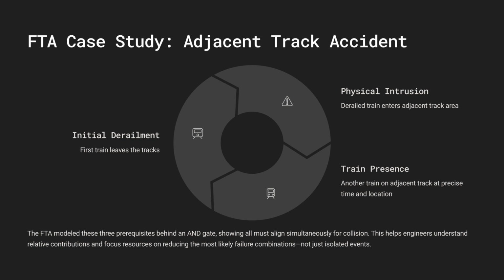Yeah, just briefly. Reliability block diagrams, RBDs, are often used alongside FMECA. They're visual maps showing how components are functionally connected in series, meaning if one fails, the system fails, or in parallel, meaning there's redundancy. They're great for calculating overall system reliability based on component data. Okay, RBDs for reliability calculation. And the other? Bow tie analysis.